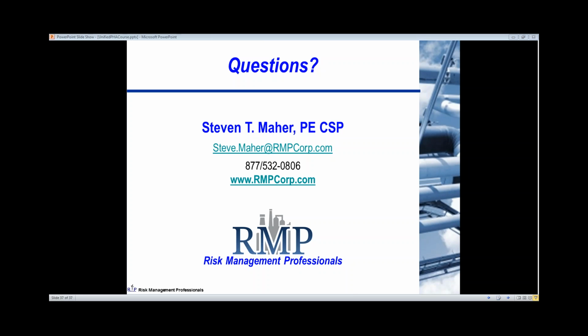The whole thing about HAZOP and LOPA is about providing balance. You're trying to do the HAZOP and LOPA to find vulnerabilities, deficiencies in the design or operations, and you're trying to take your resources at a facility and really focus it on the areas of the most importance. That's a key part of what you're trying to do for HAZOP LOPA. Everything we've discussed with respect to session organization, quality documents coming into the session, and also quality documentation of the HAZOP, it's all about that. And making sure that when you're all done, you're applying your resources in a way that focuses on life, the environment, and property.